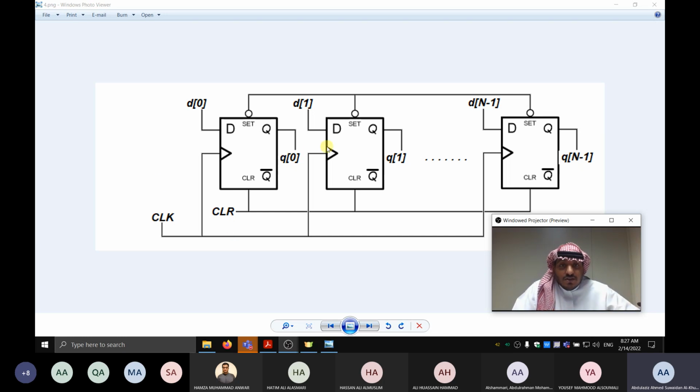So let's see. You turn on the system and that's the register in the system. And now the clock is running. So what will happen? At the positive edge of the clock, the output Q will be the same as the input. So the memory has been written. And then there is another positive edge and it's been written again. Another clock, it's been written again. You see what's going on?